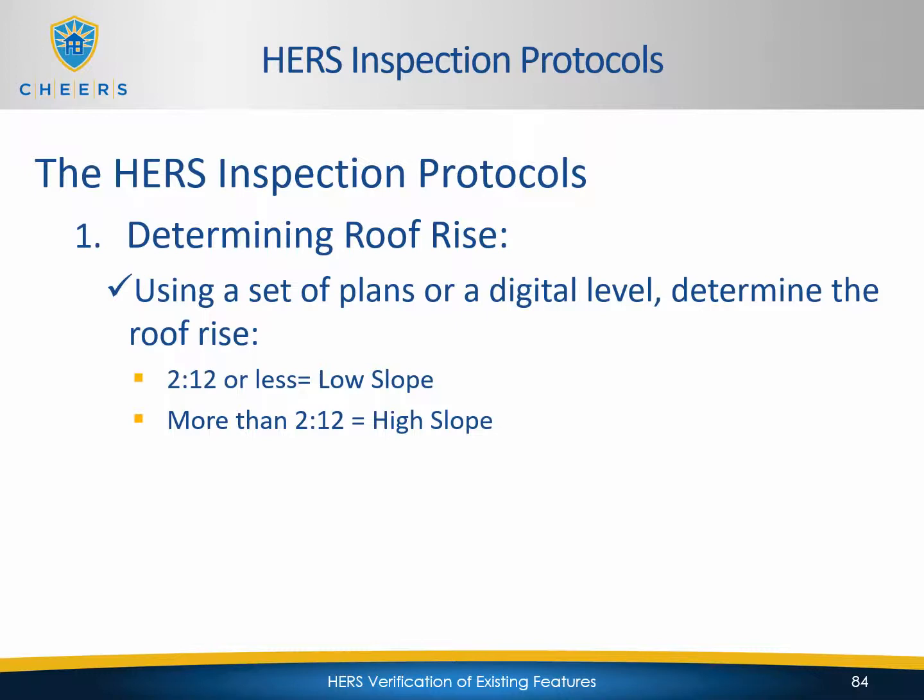You want to determine the roof rise. Using a set of plans or a digital level, determine the roof rise. If it's 2 in 12 or less, it's considered a low slope. If it's more than 2 in 12, it's a high slope.